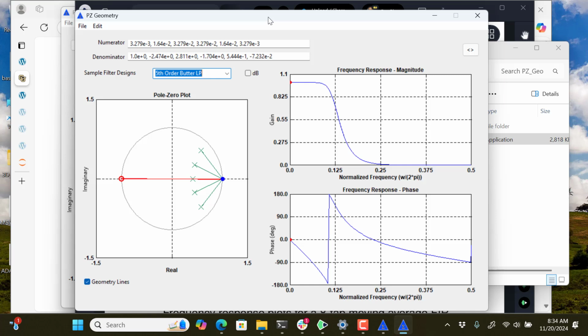So now with this Butterworth, the shape of the poles is not so elliptical. It's still scrunched, but it's not as flat looking an ellipse as it is for the Chebyshev. And you can see that looks like a nice Butterworth, nice and flat, and then all of a sudden it rolls off, and then there's a stack of zeros sitting over here. There's 5 zeros sitting at z equals -1 to balance the 5 poles that are sitting in there.